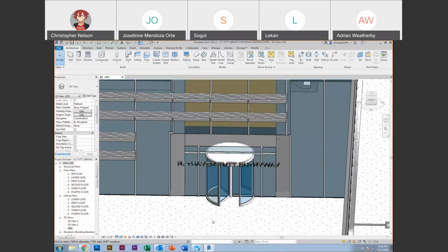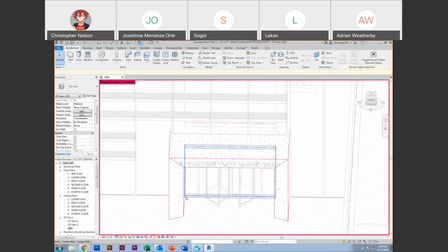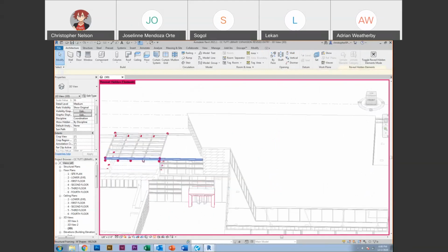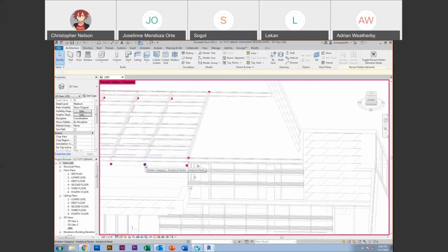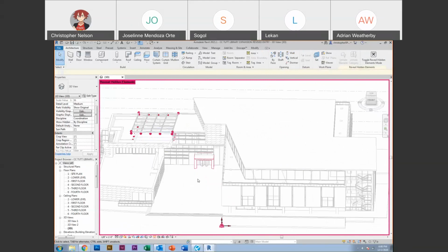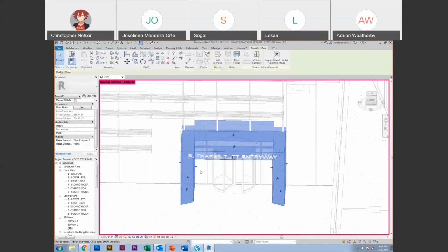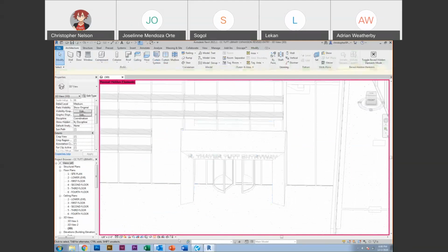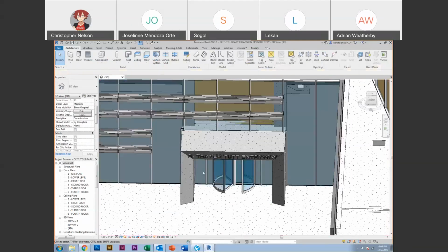Gotcha. Again, you can do the light bulb at the bottom left-hand side. It says reveal right here, kind of where my cursor is at. If you click on that, anything that's thin is going to be pink. So usually the pole lines for your structural elements are going to be these little pink dots. I'm trying to think what else is usually hidden. Your origin is usually pretty hidden. And then mass, which is this guy. And you just click on it, say unhide category, and now it's going to show up.